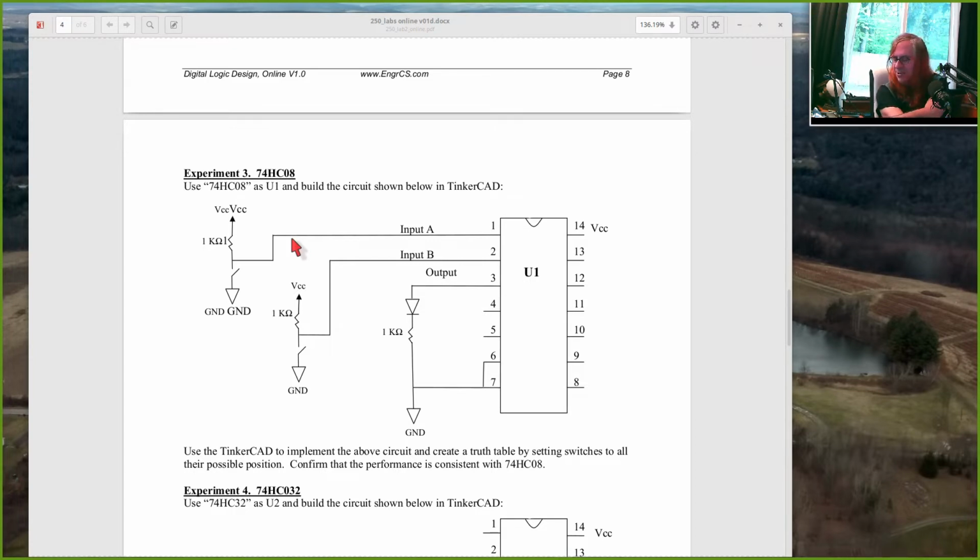That's saying, hey, I turned switch A off, but the output was 5 volts instead of 0 volts. What's going on, right? So come back to your schematic, come back to your notes, come to office hours, something. Hey, why is it that when I turn the switch off, I get 5 volts coming out? Oh yeah, because it's connected to 5 volts. Well, what happens when I turn it on? Oh, it's connected to ground. I get 0 volts. It's backwards. Aha moment, right?